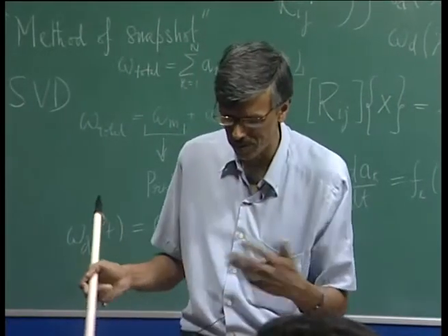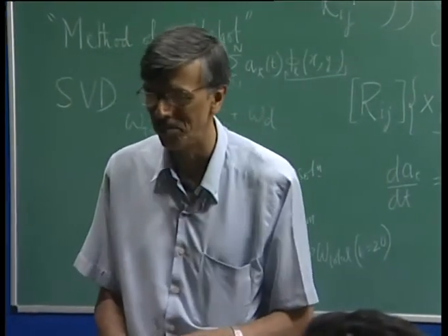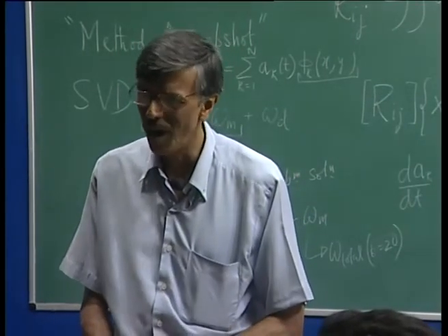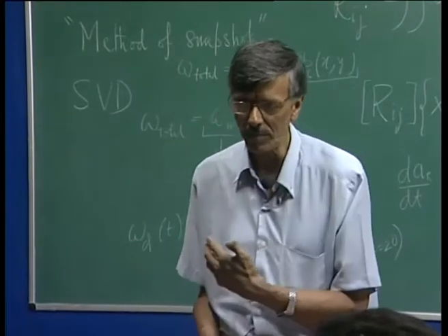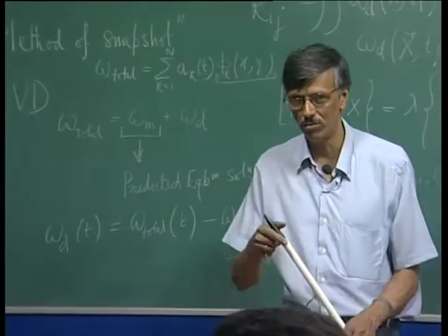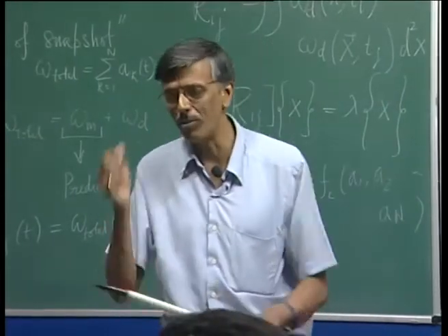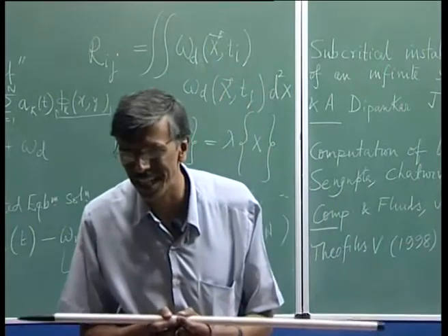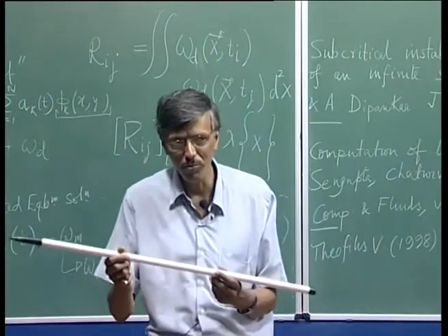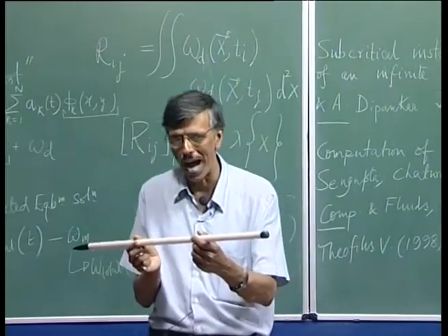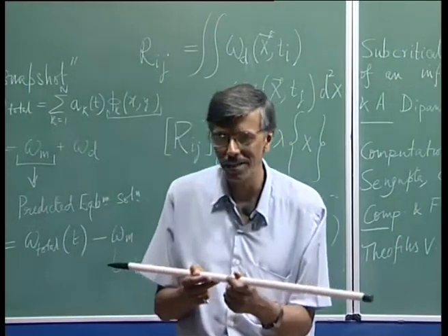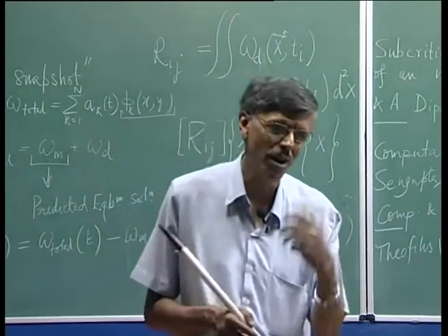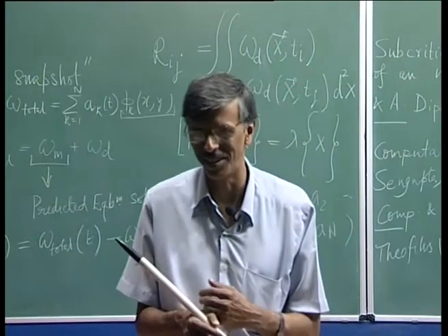We talk about it so casually, as if it was bound to happen, but in the initial phase it was very, very confusing, because we have noted that for two-dimensional sections, for aerofoil sections like what you would have in a straight wing, the flow becomes unstable with adverse pressure gradient. But when the wing was swept back, people noted that the flow transition was occurring over the wing where you actually have favorable pressure gradient, not adverse.